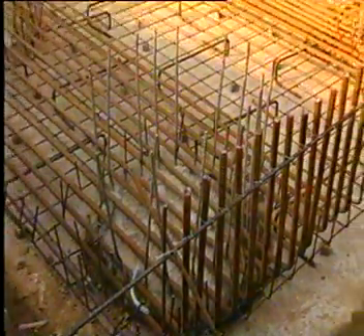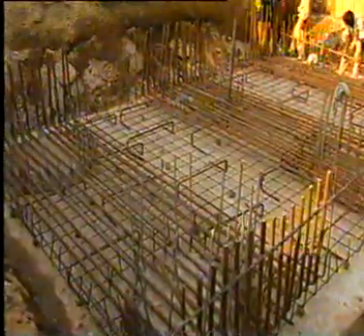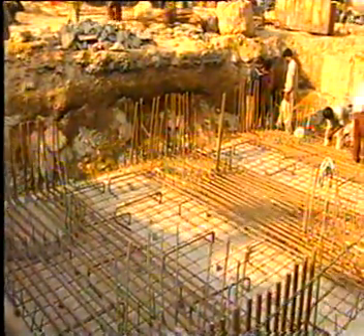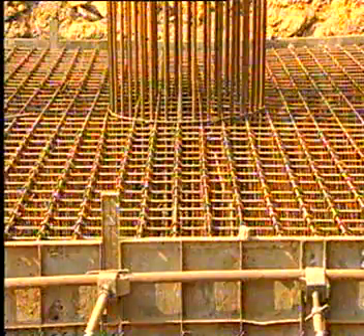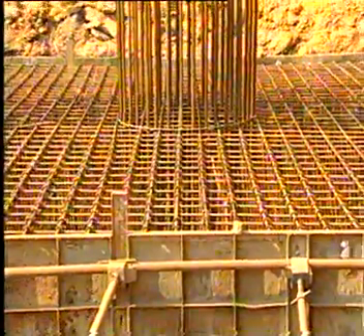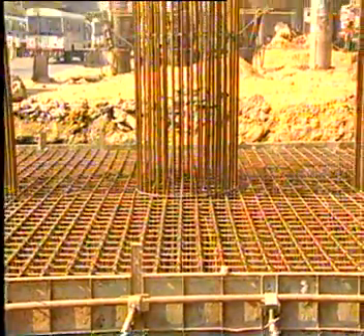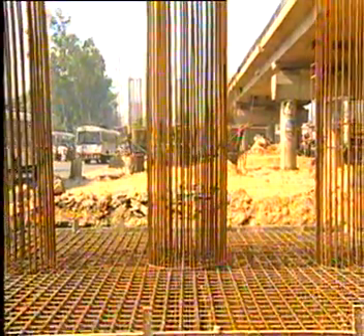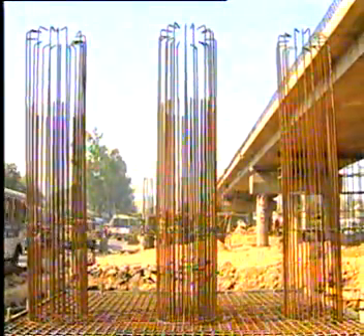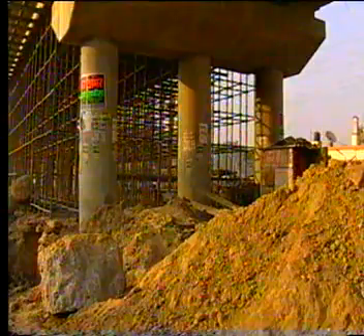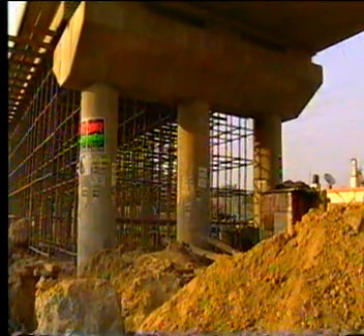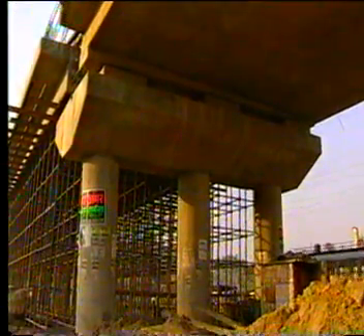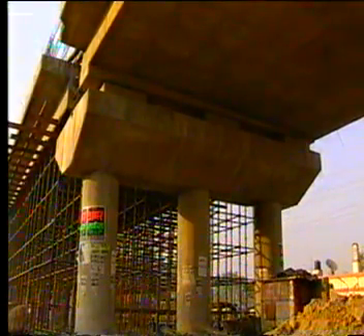Over the group of piles, the pile cap is then cast. Here we can see the reinforcement being placed for the pile cap. The columns are cast over the pile cap with proper anchorage of reinforcement from piles. Pile foundation, constructed as per the design and specifications, can cater to the transmission of loads to the soil effectively and efficiently, meeting the present-day requirements of heavy loads as in the case of multi-storied buildings, bridges and other structures.